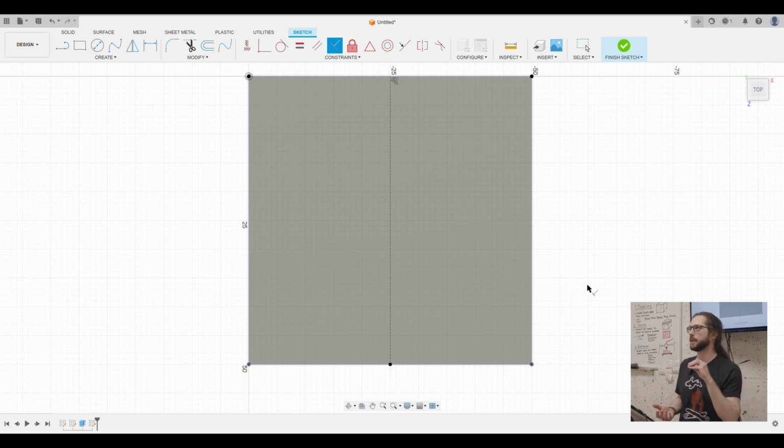Just know that if they are not fully constrained, it means that there is some way that you can move that drawing that would also satisfy whatever you've given Fusion. Once it is black, it's locked in. Like there's nothing that will be able to move it around. It is a fully defined sketch. So it is a goal, but not necessarily a necessity.